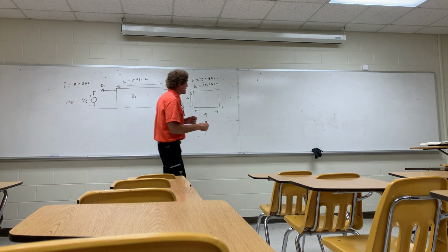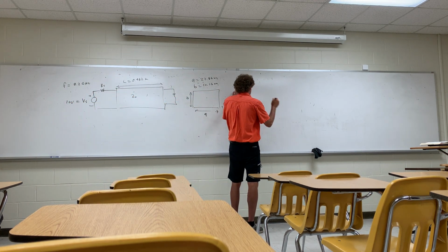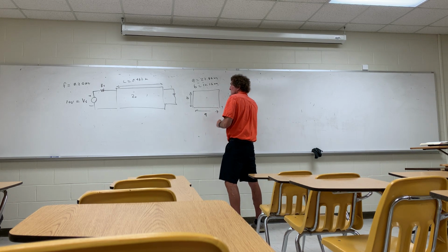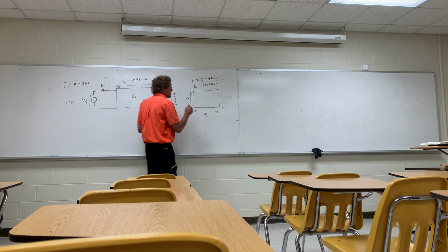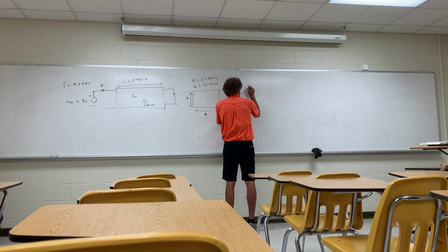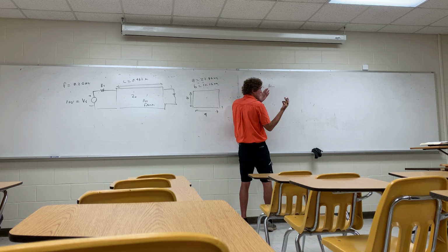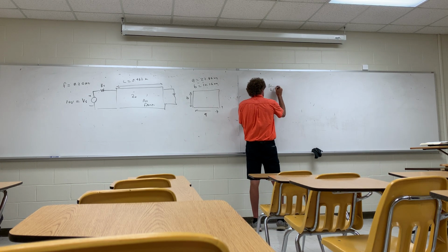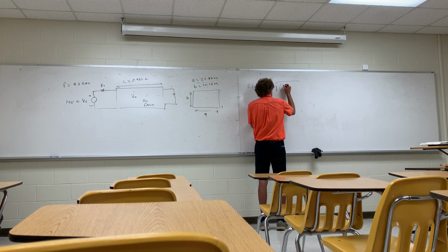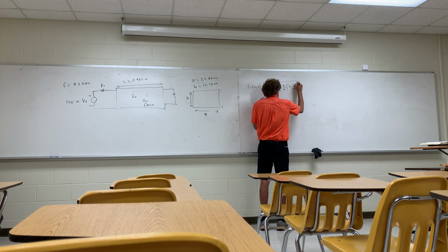And so now we find the cutoff frequencies first. Is it air filled? It is, yeah. All right, cutoff frequencies. I'm using c because it's air. Otherwise, I put 1 over the square root of mu epsilon here, divided by 2, times the square root of (m over a) squared plus (n over b) squared.